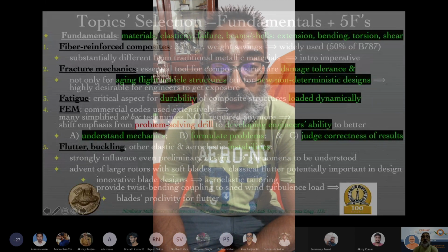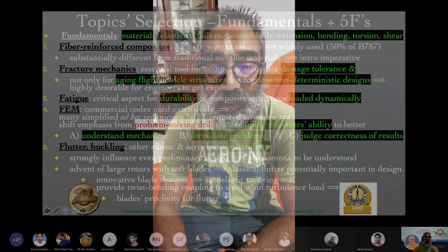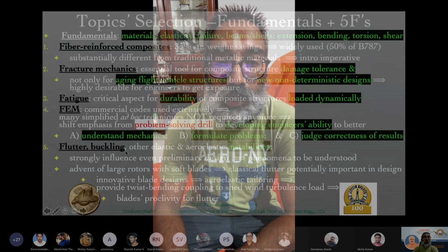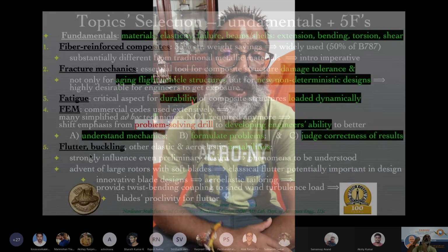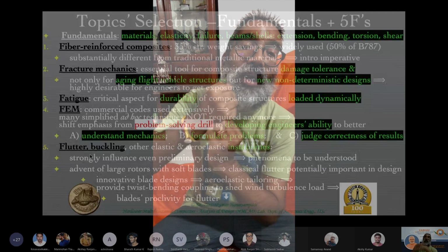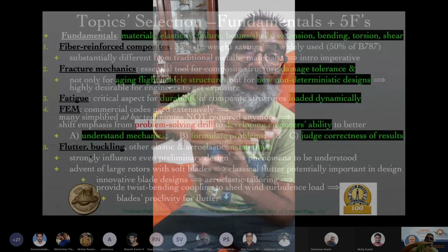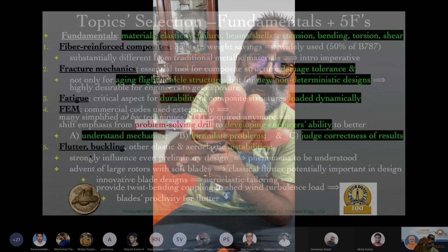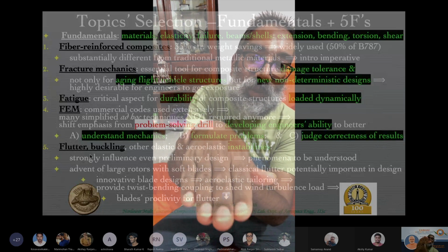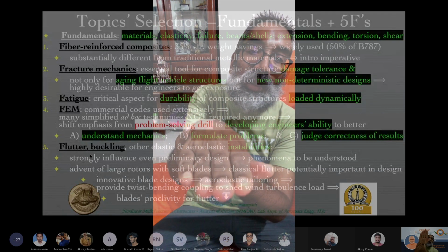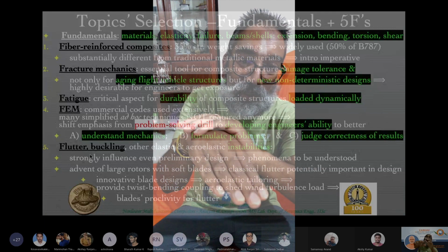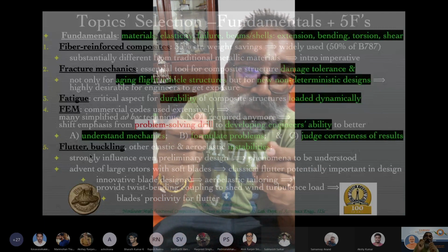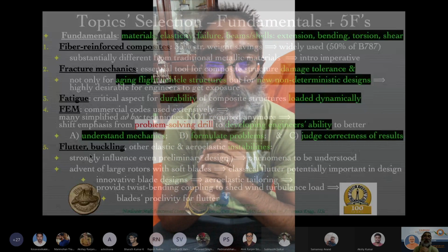In other words, because we have thin-walled beams and thin shells, those are prone to instability, especially under compressive loads. And these compressive loads need not be actual compression in a bar, for example. It could be bending, where in the case of the wing, when the wing lifts and therefore bends upwards, the panels on the top surface of the wing will be undergoing compression. So there can be local buckling that is happening there.